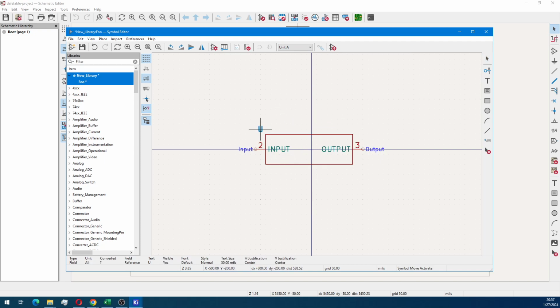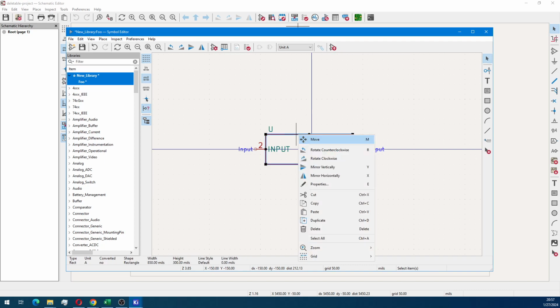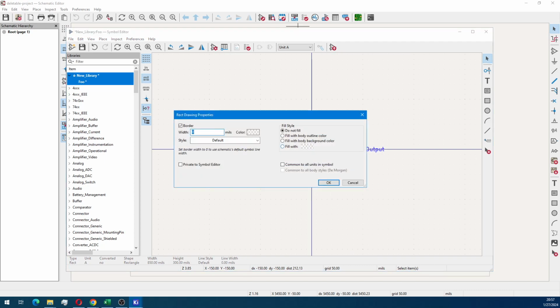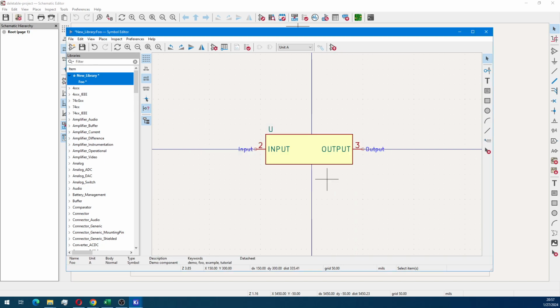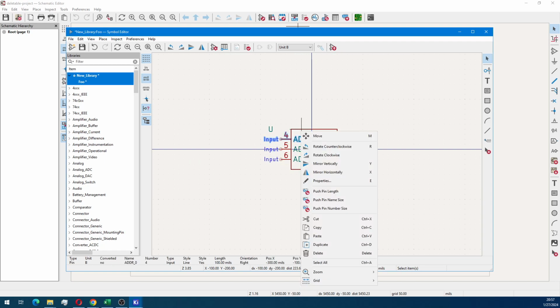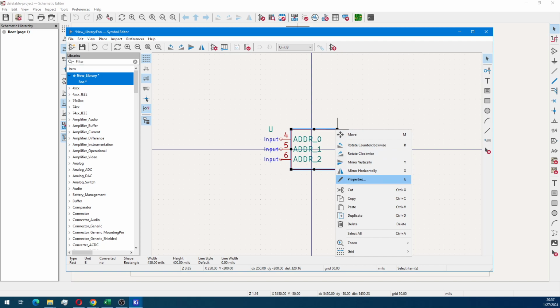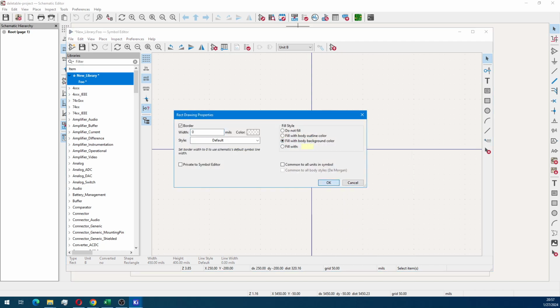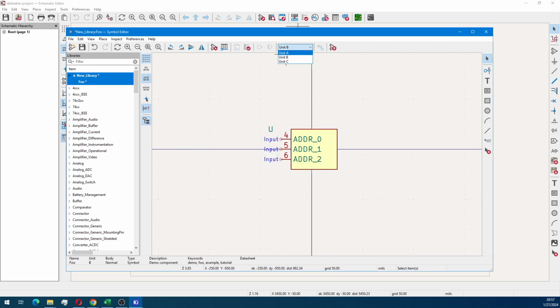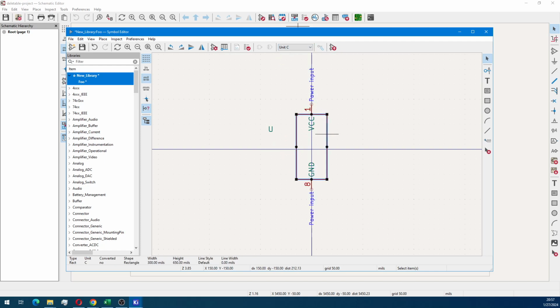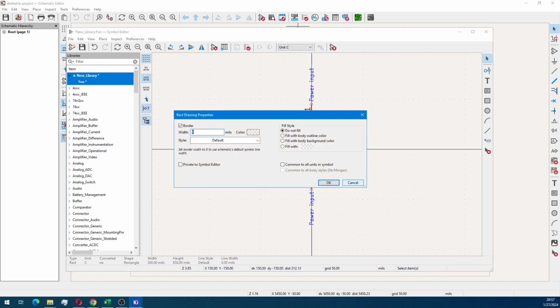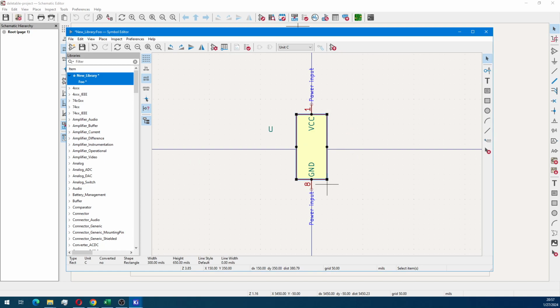Now finally, there is what's called the KLC, KiCad Library Convention. The convention is if the function of your device isn't obvious from looking at the shape, what you traditionally do is you right-click it and you set the fill color to the background color. So if you're following the default color scheme, that's going to be yellow. And if you're using one of those custom themes that I showed in, I believe it was part 0 or 1, it's just going to be some other color.